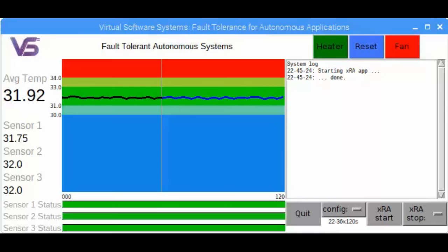To demonstrate continued process control despite a hardware failure, a failure was introduced in the controller running replica number 3, as shown on this display screen video. Following a very brief interruption for analysis, all status bars turn yellow. The X-Ray replicas determine the source of the fault by X-Ray consensus management and remove the non-concurring replica number 3. Process control continues with the two remaining replicas, number 1 and number 2, whose status bars remain green.